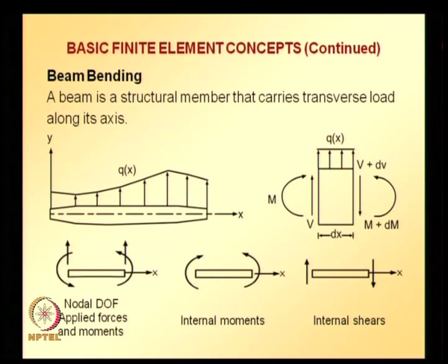One important thing is sign conventions. The conventions adopted for positive directions for transverse displacements, rotations, applied forces, and applied moments are shown in the slide, along with nodal degrees of freedom, applied forces and moments. The sign convention for internal moments and internal shears is also shown there.